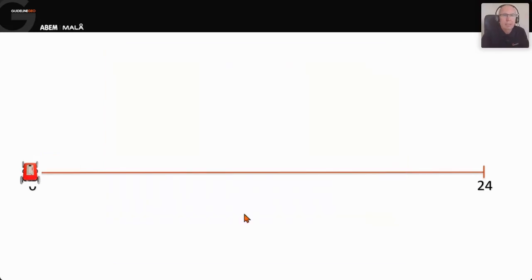It will then go back to the standard 2D screen. You then continue your line of data collection until you get to the end, and then you can stop the profile at that point. We then move the radar over. We're going to do a zigzag fashion of data collection. You can go in one direction if you wish, but more effectively in this case, we're going to go in 2 directions. So we're going to zigzag across the site.